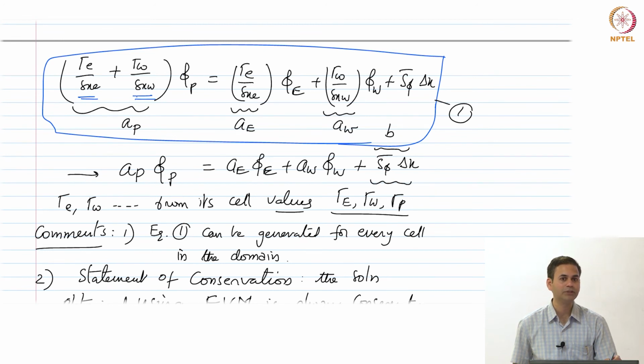Whereas in the finite difference methods, we had a 2 gamma by delta x square, right? Why is the difference? Taylor series, because we have integrated these equations now, right? We have integrated the equation, so the order of the derivative has now decreased by 1, right? The d square terms have become d by dx. Because of the integration, we got rid of 1 delta x there.